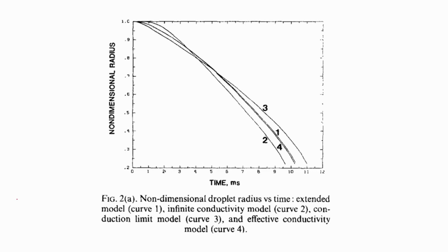We said that the model can be solved numerically. This is basically the numerical solutions that you see over here. So, this should be interesting. Here some of the basic parameters are T naught, the initial temperature, is 300 Kelvin. This can be anything, you can actually do your own model, but this is just to give you an idea. The external temperature is about 1500 Kelvin. That is more like a flame and things like that. The external pressure is about 10 atmosphere. So, it is a high pressure chamber.